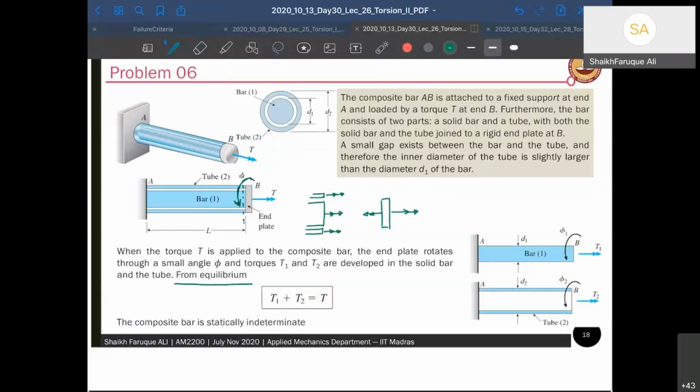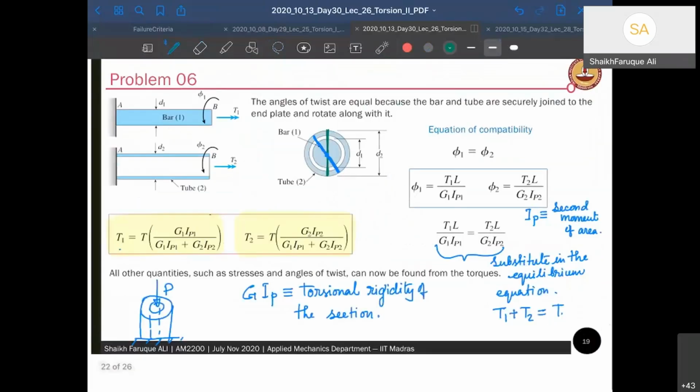All right. Okay, so that's how you solve this. But the objective of giving this kind of problems is that they are solved either with the flexibility method or the stiffness method. You have to understand which method I've used, and solve with the other method to make yourself comfortable. The point I was trying to mention is that load sharing happens based on the rigidity share that they have. That's very important to know, right? And that gives you an easy check as well as easy solutions when you have many members together.